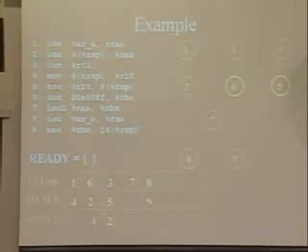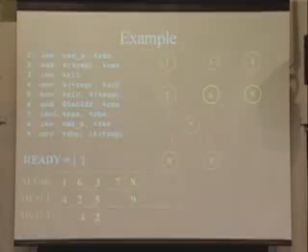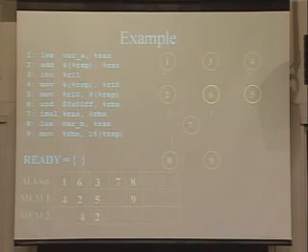So what happens is now, this is the order the machine can execute in. Since superscalar will figure it out, you have to issue instructions probably 1, 4, 6, 2, 3, 5, 7, 8, 9 or something like that. Order the instructions in that order, do that, and then you'll get this very tight schedule in there. So this is what you have to do in here.